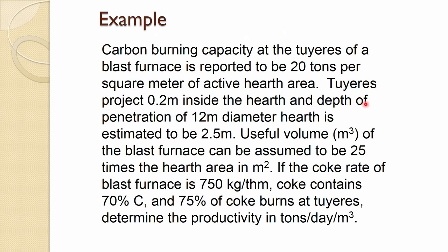So, this depth of penetration means the raceway depth in a 12 meter diameter hearth is about 2.5 meter. Useful volume of the blast furnace can be assumed to be 25 times the hearth area in meter square.